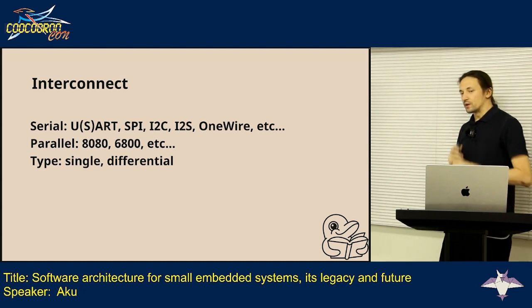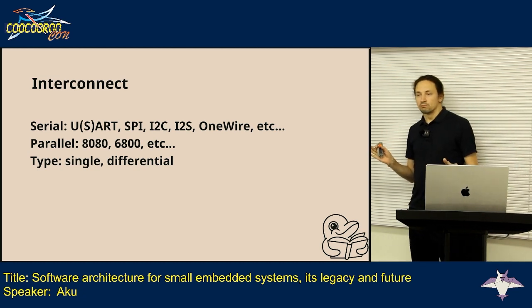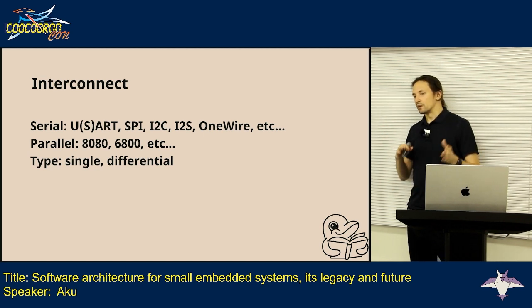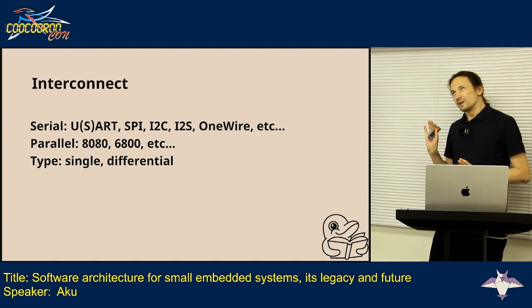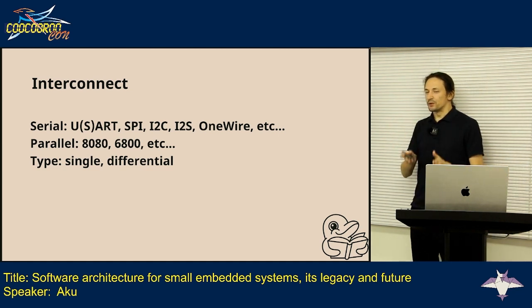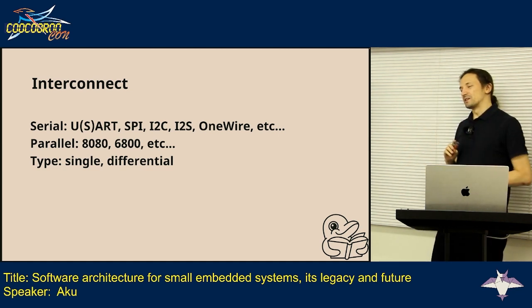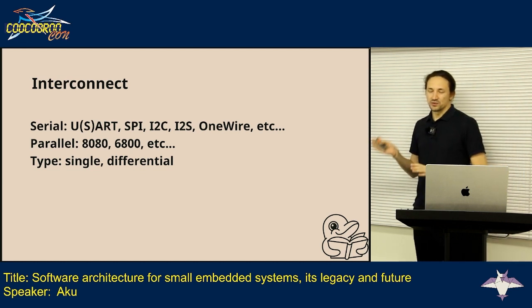It will be one isolated CAN bus, and then we have, let's say, lights and the body. That is usually a second one, less isolated. We do care about errors in the first one, and for the second one, if something goes wrong, it's okay.